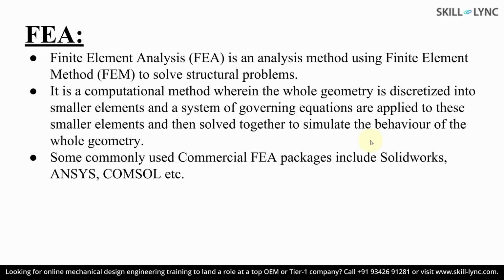Finite element analysis is popularly abbreviated as FEA. In this analysis method, we use the finite element method to solve structural problems. Here, the whole model is discretized into small elements which consist of nodes on which the governing equations will be solved. Once the governing equations are assembled for the whole model, several matrix solving techniques are employed to solve for the unknowns. Once we know the values for displacement, we derive the stress and strain contour plots for the whole model.